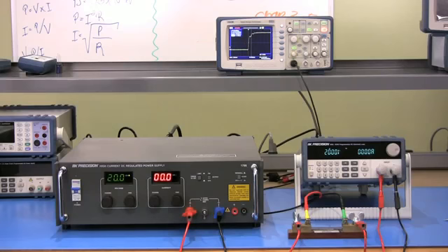It is important to note that while we define slew rate to be from a change of 0 to 100% of the load's maximum input current, slew rate may vary if measured with a different transition range, such as 20 to 50%. Keep this in mind and measure your slew rate accordingly based on your application.